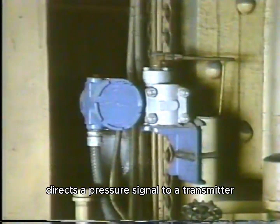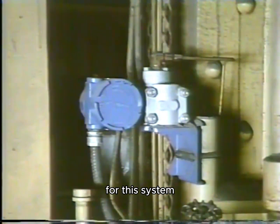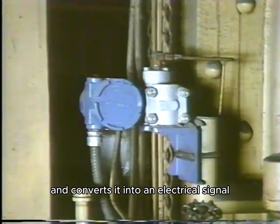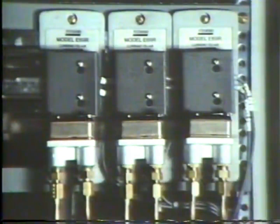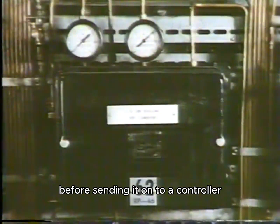The other tap directs a pressure signal to a transmitter. This transmitter functions as both the primary and measuring elements in the control loop for this system. The transmitter senses pressure changes, measures the change, and converts it into an electrical signal, which is then transmitted to a converter. The converter changes the electrical signal into a pneumatic signal before sending it on to a controller.